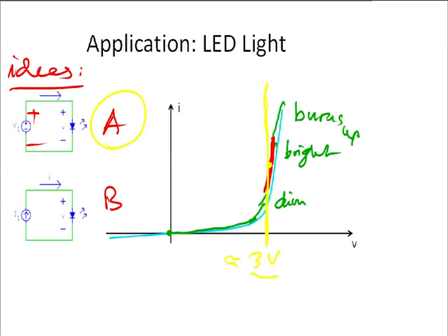So, well, we could do that. Would we become famous as circuit designers? Well, maybe infamous. So let's come up with the right solution. This time, we have a current source that pumps out current I1, and we can again adjust this current. The current source has a characteristic that looks like this, and the value of this current is I1. So where does this thing operate? Well, it operates at this point here, where the intersection is. It doesn't have to be where the yellow line is, but that would be our choice.